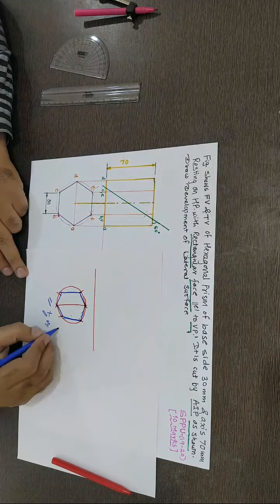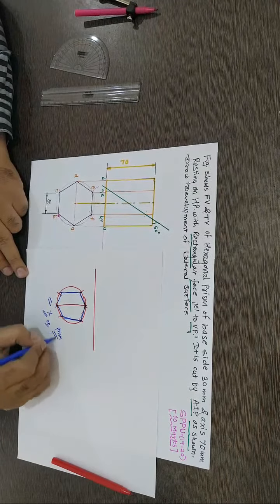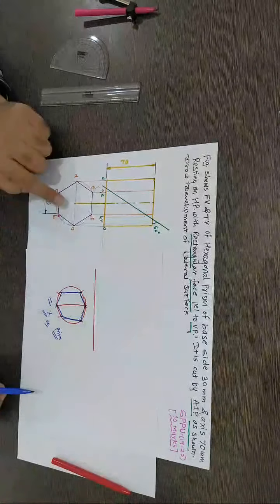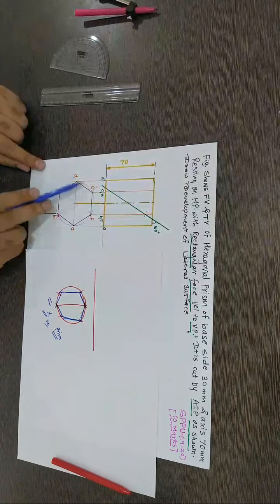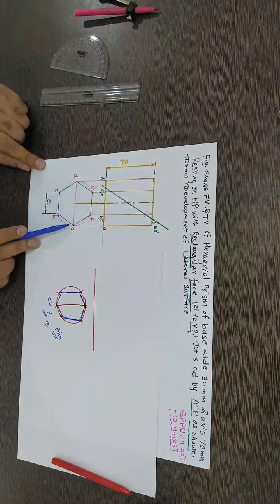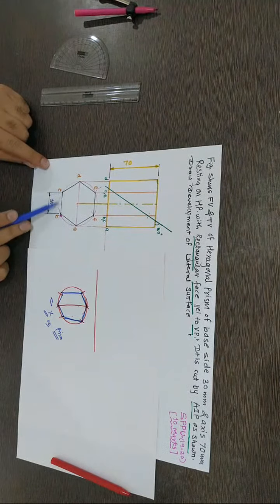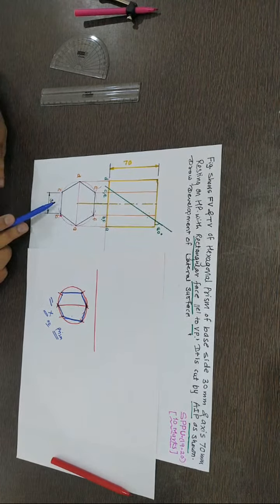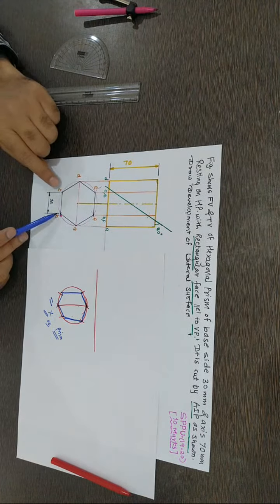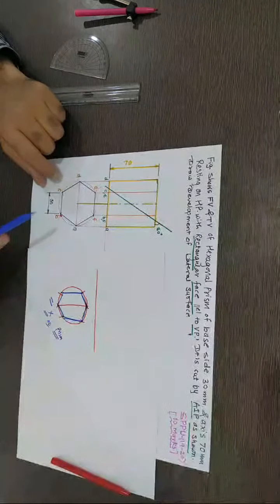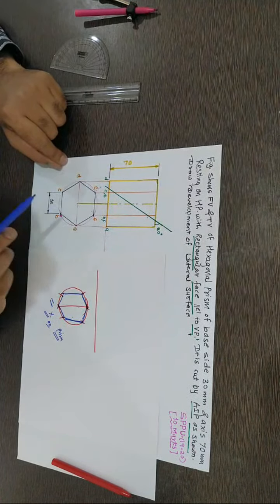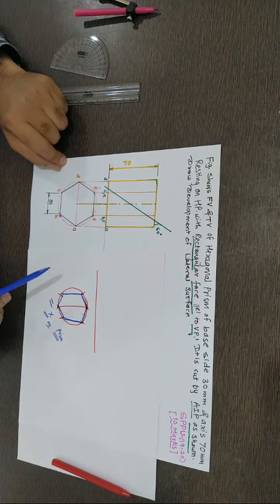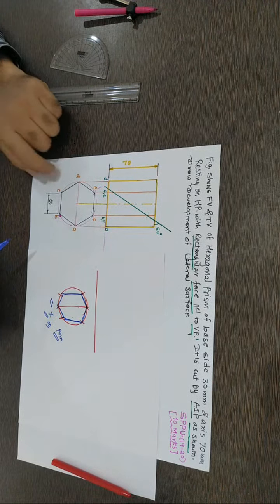Now, as it is a prism problem, you understood the difference, and why I have drawn the hexagon in this position only, keeping this horizontal reference diameter. In that case BC is a base edge, and similarly the corresponding top points form a face, as well as EF, which is parallel to VP. VP means vertical plane. So this should be the position.